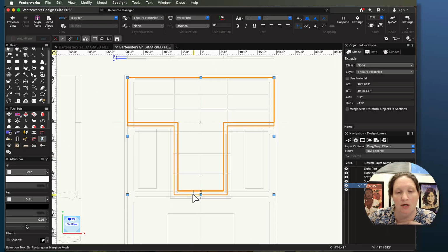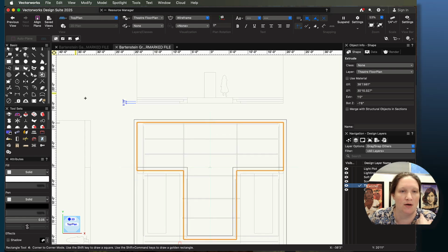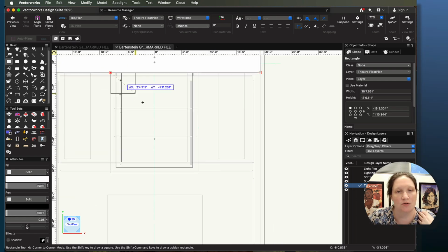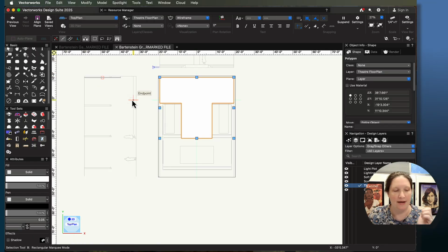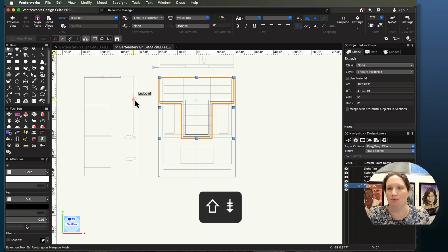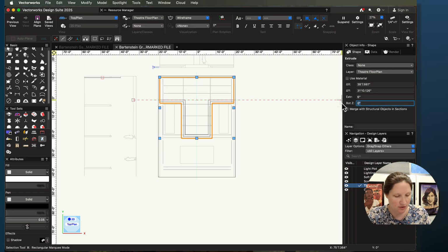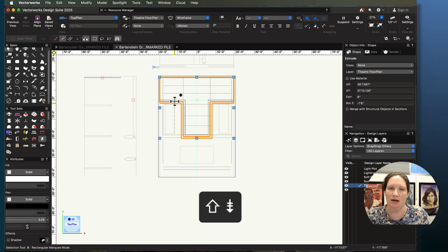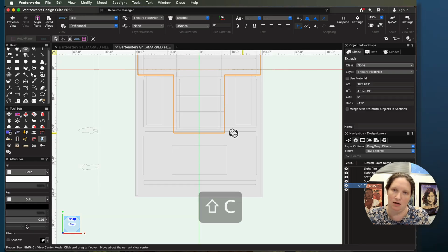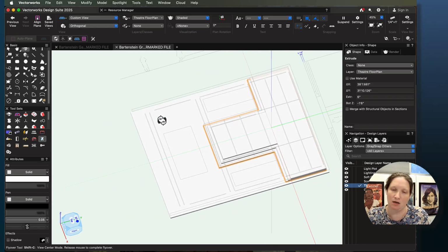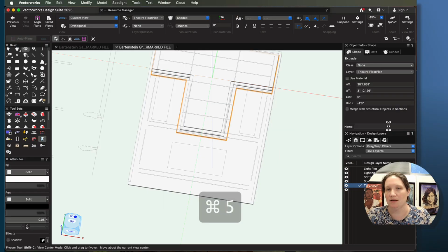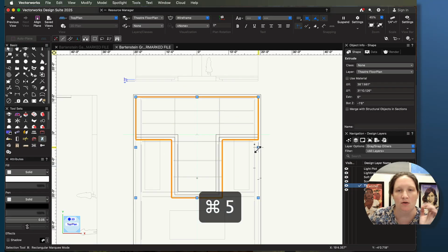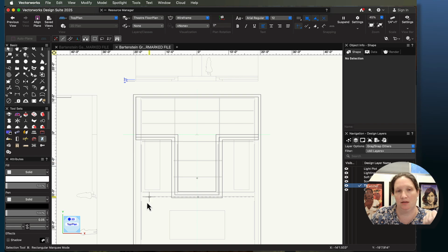So now one more time, we're going to get our last step and assemble those into the stage. So let's go ahead and draw. Great. And then we'll extrude this only 6 inches. But we'll give it a bottom Z down at that lowest level again, minus 1'6". And now we should have our 3 steps. Great. Okay. Yeah, save it. Great. Thank you. Okay, so now we have a floor for the floor, like that's all the way at the bottom. We have our 3 steps, and we should now be able to do our walls.